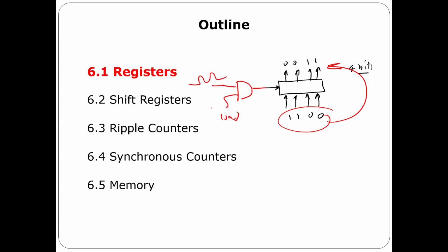So when load is equal to 0, I'm going to have 0 here, and because there is no clock, whatever you have here is not going to be written. If I put 1 here, I will have a clock here. By this way, I can use load as enable or disable. The answer is yes, you can do that.